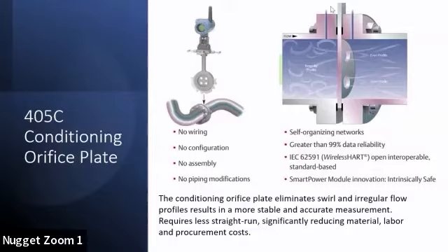And as you can see, this is how we can sell it. That goes up to about a 12-inch line size. If you need a bigger one, we have a separate plate. But this is a nice, convenient way of getting it all in one and getting that information out. So basically the 4 holes just do a conditioning on the downstream side, and on the upstream side is where you're going to get your pressure measurement. So between those two coming out, you've got the 2 bits of data you need.